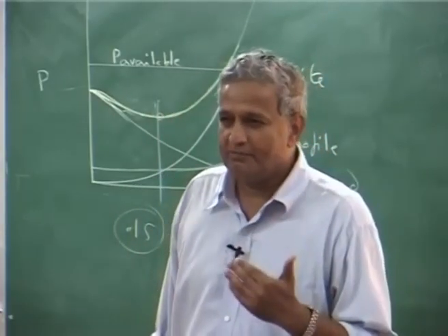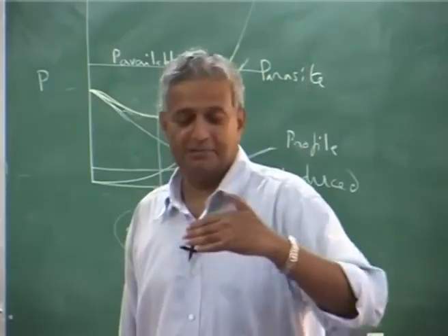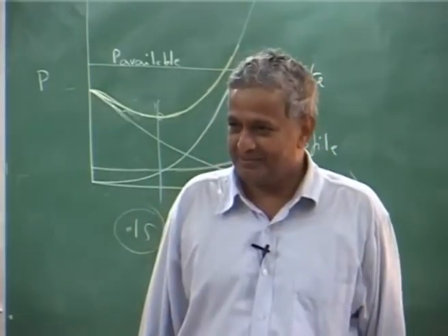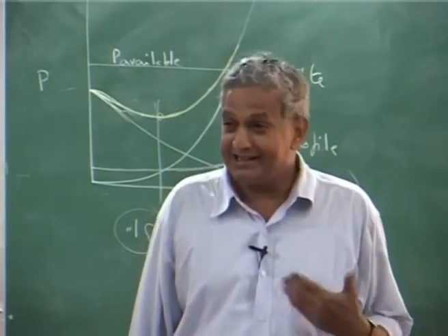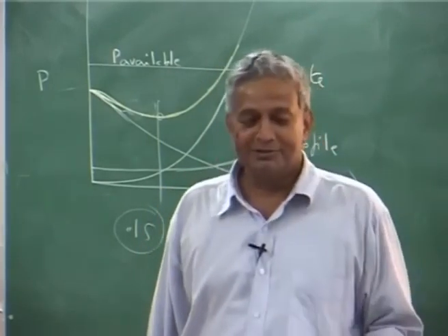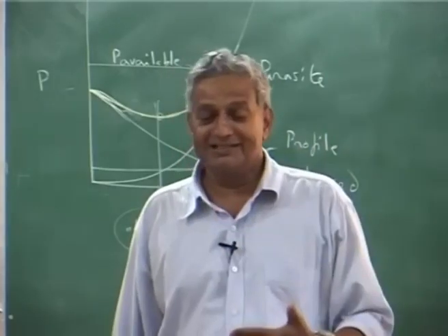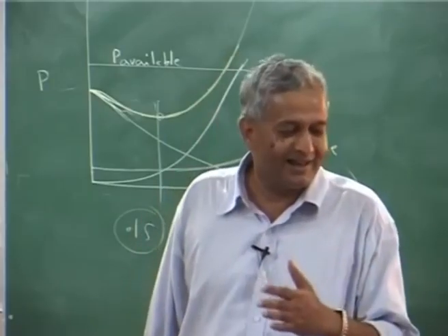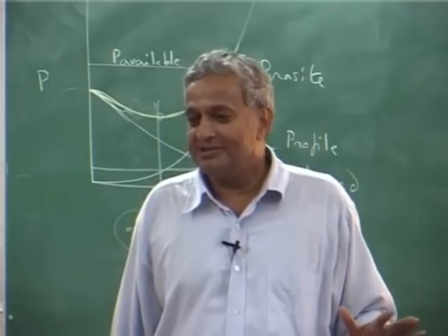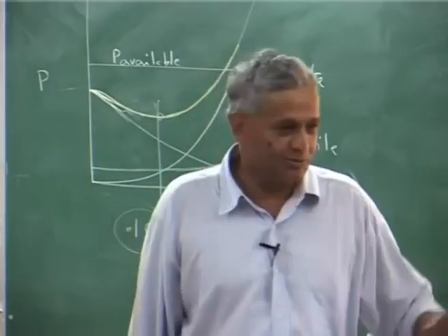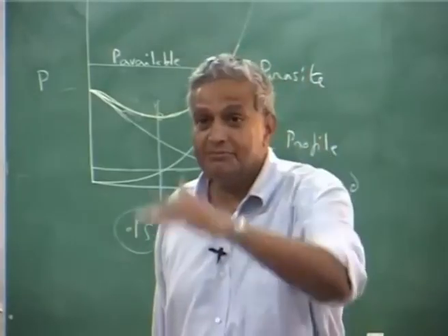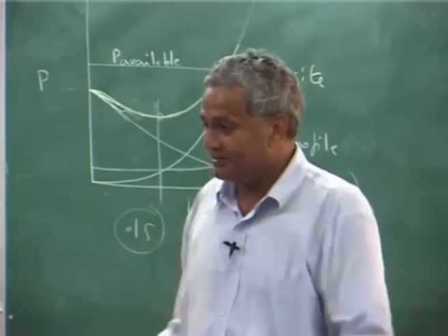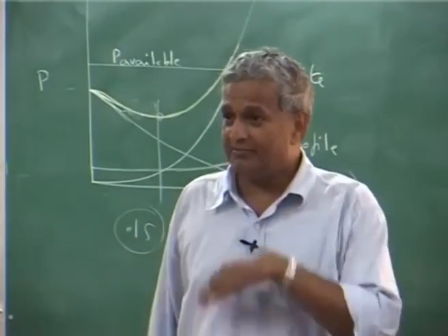The best design is one where your flight envelope or the max speed is restricted because my power is not there, so I am not able to fly. You follow? On the other hand, it is not like that. You may have power, the engine can give, but you say, oh, I cannot go, my forward speed is restricted because I have a lot of vibration. That happens in almost the majority of the helicopters, because we are all talking about mean value, mean value, mean value. We have never mentioned anything about the vibratory loads, because we took an average, but the vibratory loads are the ones which contribute.